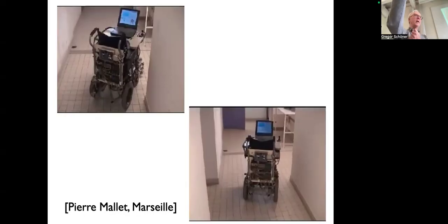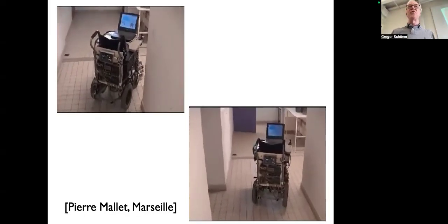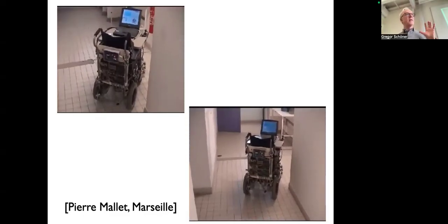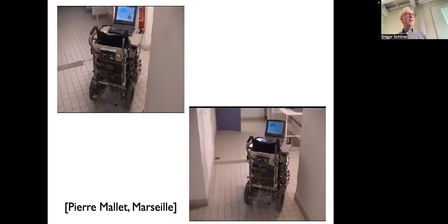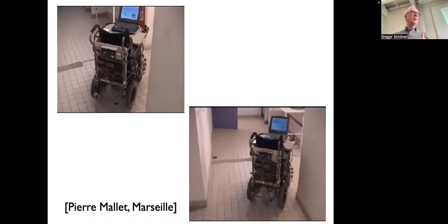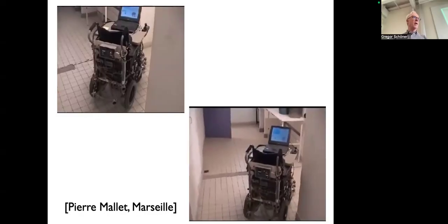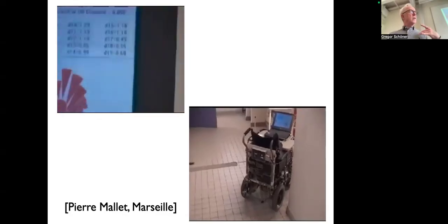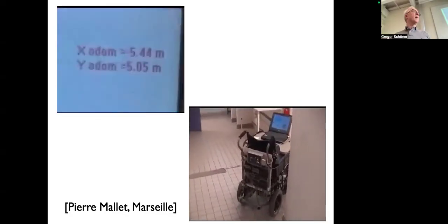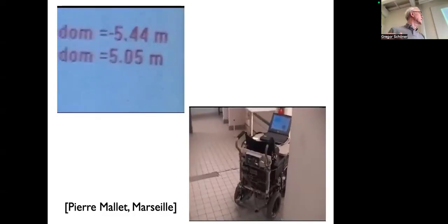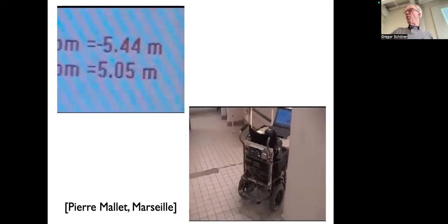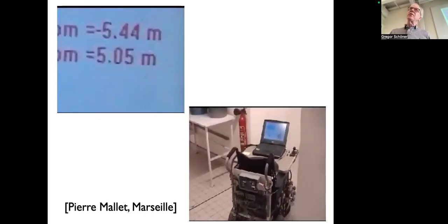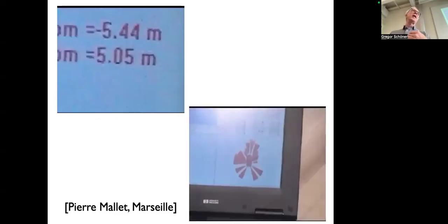Something in front moves barely. Like if you look at the moon, it barely moves when you drive around. And then if something gets very close, right? So you can get an estimate from that, the closest kind of thing that you want to deal with, that your avoidance will ever generate, and if it's at 90 degrees, then you can compute how fast it will move in an angle. It will move at an angular rate, right? And so then that's the speed at which I have to track the attractor.